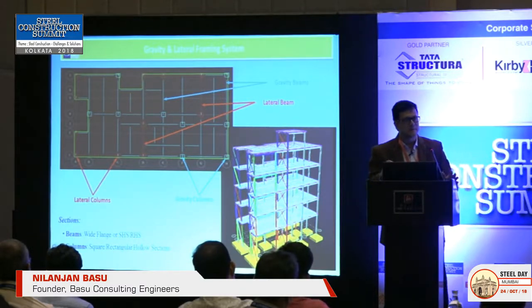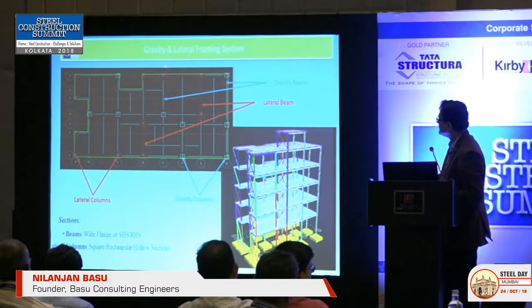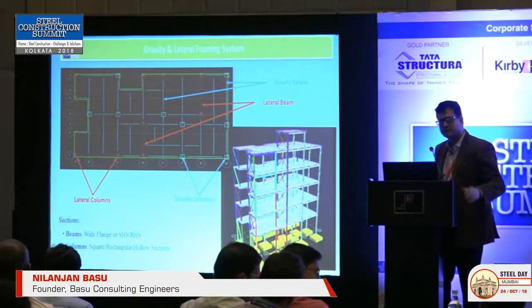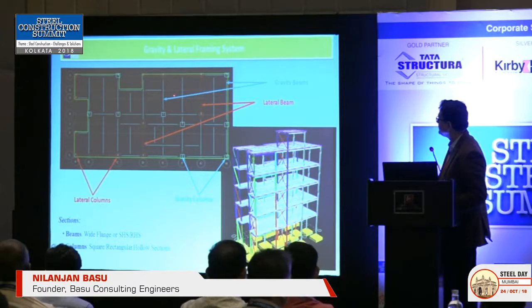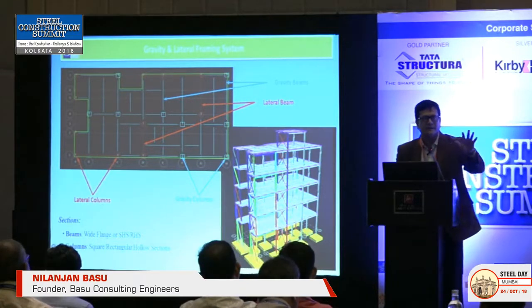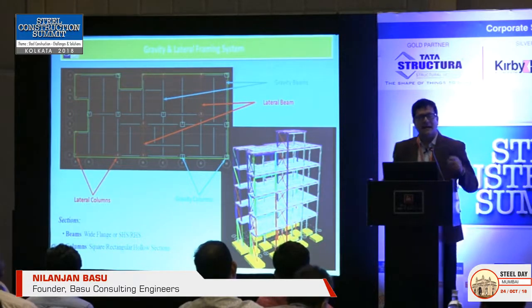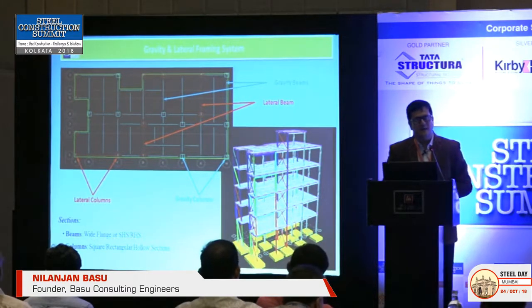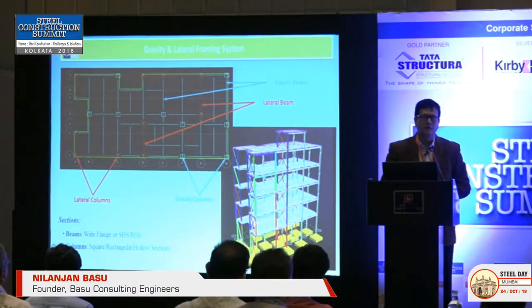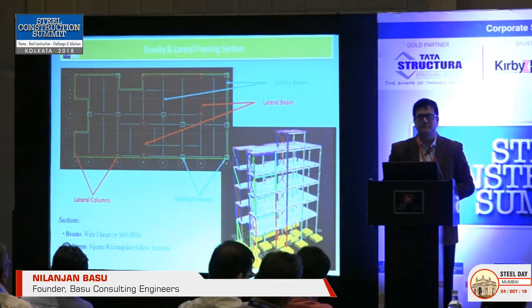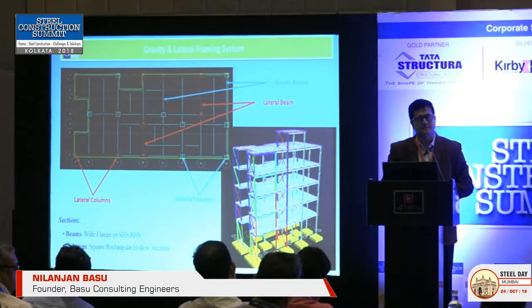That's for sure. Because once you define this system, see this red mark, the red columns and the red beams are the lateral grids. They take in the lateral forces. And the ones in gray, they are taking in only the dead loads and live loads. So you are not actually increasing all the beam depths. And I would place the lateral frames where I would have a wall below, or a solid wall where I don't have any openings, or where I can place a bracing system.